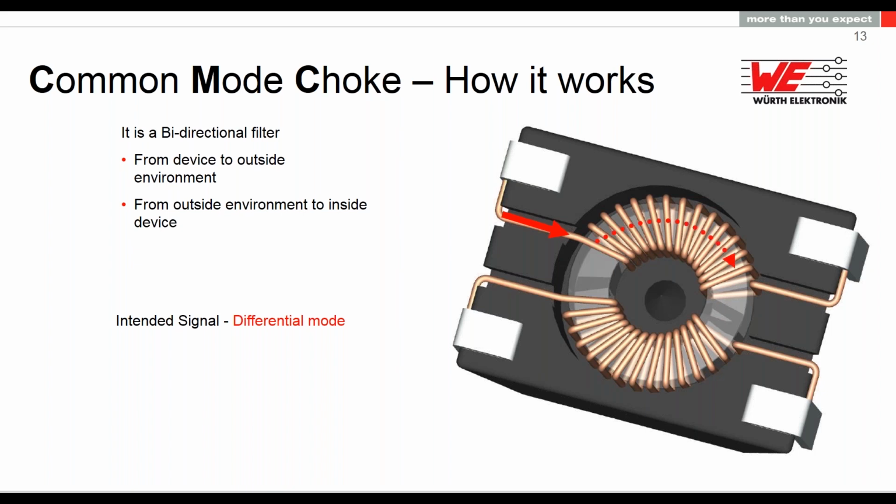Now, the current goes through the inductor, goes to the load, and comes back, the same current. Now you have to take your right hand and put it again in the direction of the current, and you will generate with the rest of the fingers the opposite magnetic field. You will have now the compensation of the magnetic field.